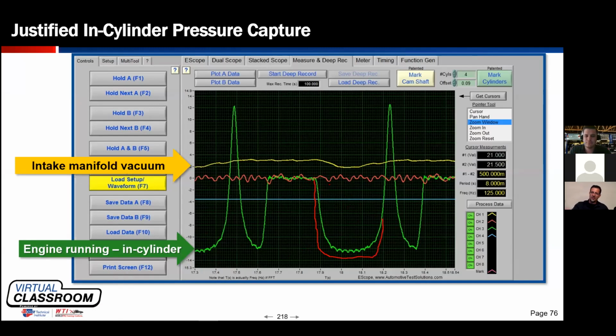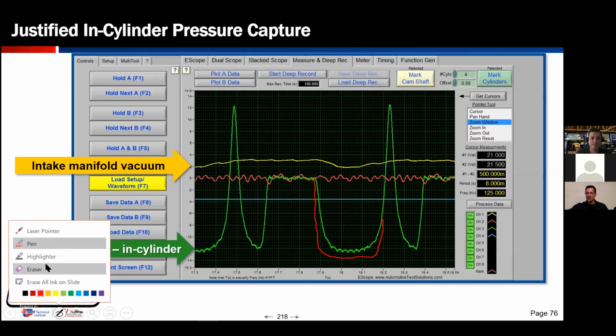If I had a pressure transducer screwed into the syringe and I drew down with it sealed, vacuum is going to strengthen over time till I get to bottom dead center, and then it's going to change direction. The vacuum will dissipate, and once we reach atmospheric, it will turn to pressure once we cross that threshold of 0 PSI. So the significance of the rounding is the piston descending and then ascending against closed valves.